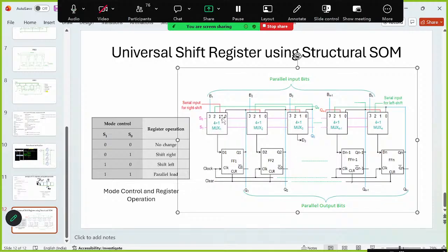So what you will do? You will write code for the 4:1 multiplexer using the behavioral style of modeling. Then you will write code for the D flip-flop using the behavioral style of modeling. Then write the main program, declaring both these components in the main program between the architecture and begin. After that, with the help of port map, try to connect the inputs and outputs as per this architecture, and then verify whether it fulfills your requirement or not.